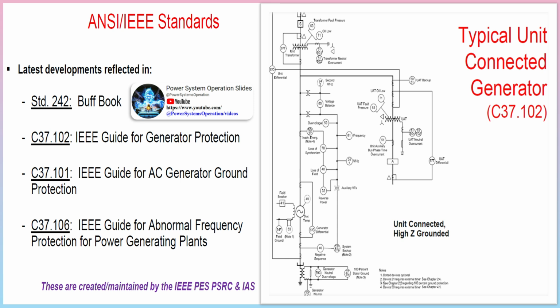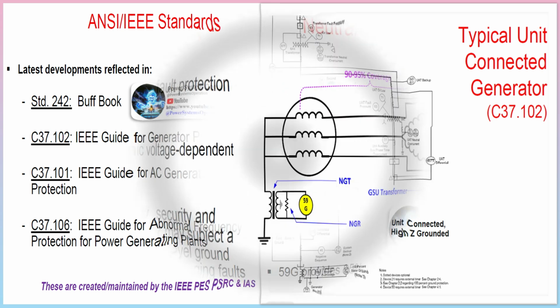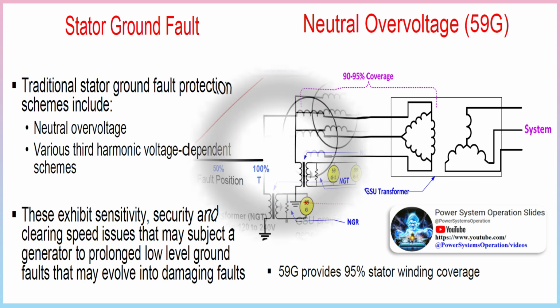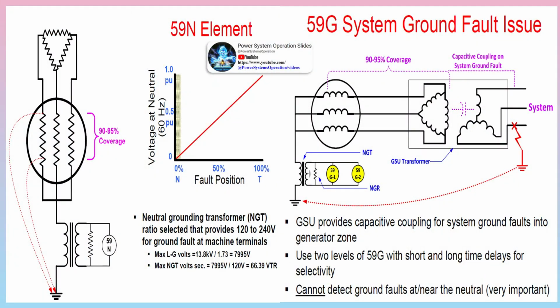Types of generator grounding: high impedance. Creates a unit connection, with system ground source obtained from the GSU, and uses the principle of reflected impedance. R_NGR equals neutral grounding resistor resistance, R_R equals reflected resistance. Ground fault current is typically greater than 10 A. Types of generator grounding: compensated. Creates a unit connection, the most expensive, with a tuned reactor plus GSU and grounding transformers, and system ground source obtained from the GSU, using reflected impedance.